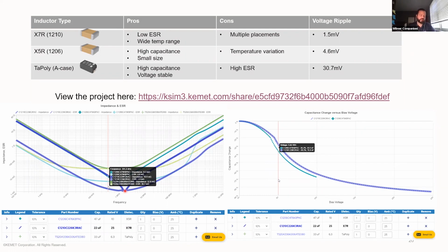And I forget exactly off the top of my head what those particular conditions are that we use in the simulation case. We can try to get back to you on that. But yeah, if you were to use, you know, 1/4 ounce copper, you're going to get a lot more temperature rise than if you use some really heavy, like 2 ounce copper or something like that, right? Because you have much more place for that heat to go through.